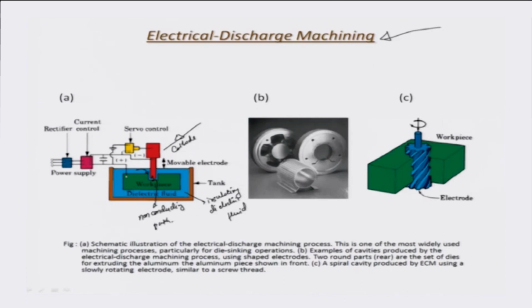So, as this path is non-conducting and you keep on charging this potential to a higher negative potential, there is a tendency that the medium, which is very small in this case, which is an insulating medium, breaks down, and there is a discharge which happens because of the charge difference from the cathode in this particular case. So, a discharge is typically a momentary stream of electrons which is released by the cathode, and they are driven by the field and the positive potential of the